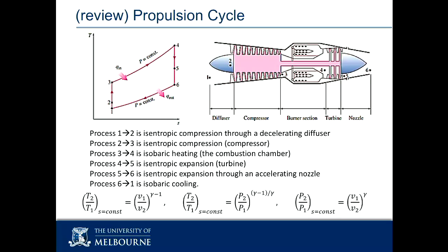These equations, when you're dealing with air, you're in an ideal gas. When you're dealing with an ideal gas on an isentropic process, you have three friends for working out what happens over an isentropic process. So if you need to determine the properties at state 2, and I tell you it's an isentropic process, these are your map to get there. And either you'll be given a volume ratio or a pressure ratio to be finding temperature. So down here, T2 on T1 is V1 on V2 to the gamma minus 1. T2 on T1 is P2 on P1 to the gamma minus 1 on gamma.